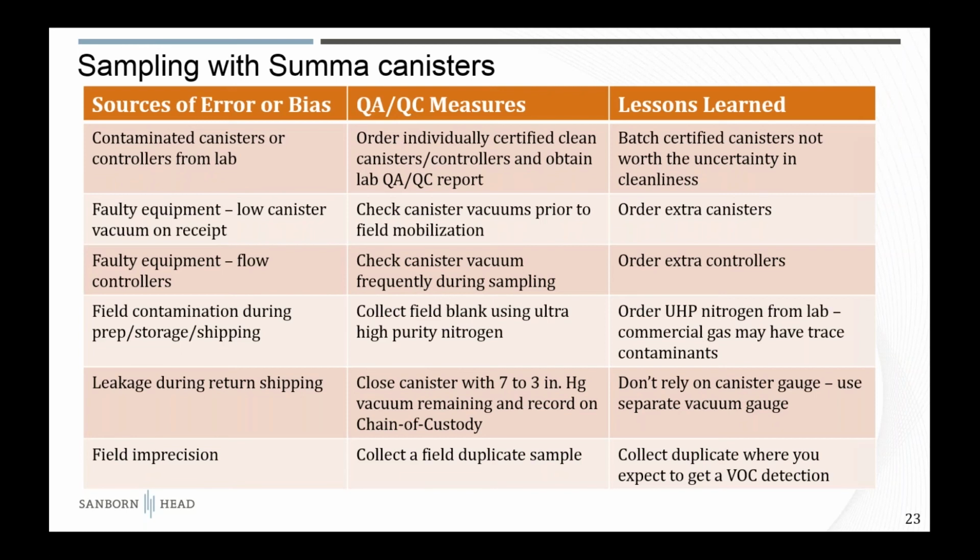So this is a similar table to the previous one, focused on SUMMA canisters, and this goes for all media, anything you're collecting a SUMMA canister with: soil, subslab vapor, or indoor air. The labs aren't going to want to hear it, but one source of potential error or bias is contaminated canisters. Canisters are reused over and over and over again.